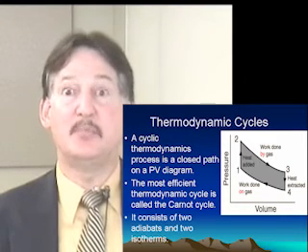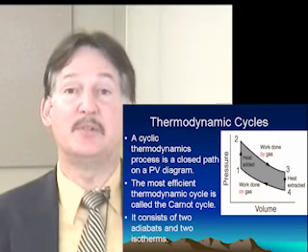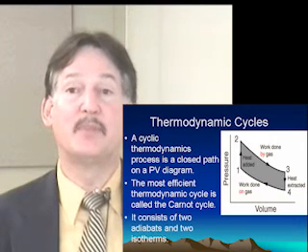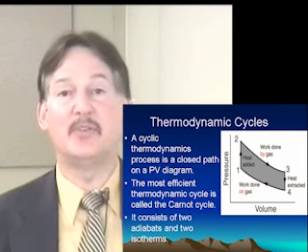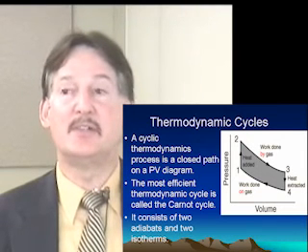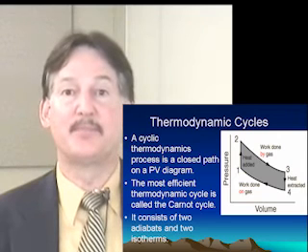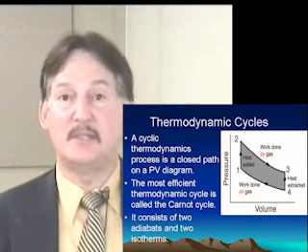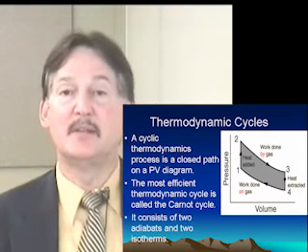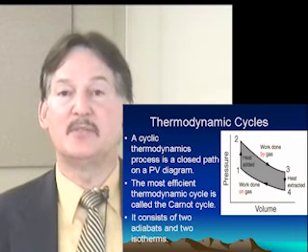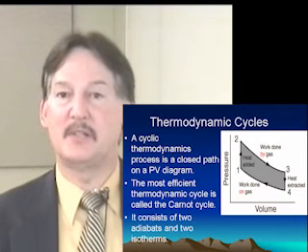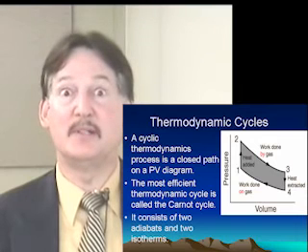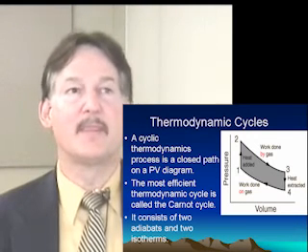Okay? Now, step 3 to 4, notice once again, it's isometric at constant volume. We have a depressurization going on. In other words, the pressure is dropping. And in order for that to occur, heat must flow out of the system as energy is taken away and the pressure decreases. Okay? That means the temperature must be dropping because we've got the volume fixed, the pressure dropping, and therefore the temperature has to drop correspondingly.